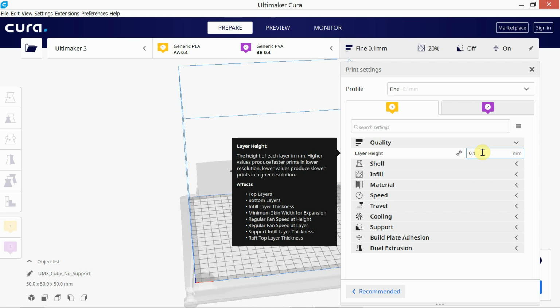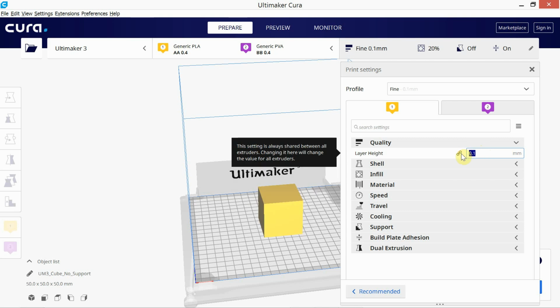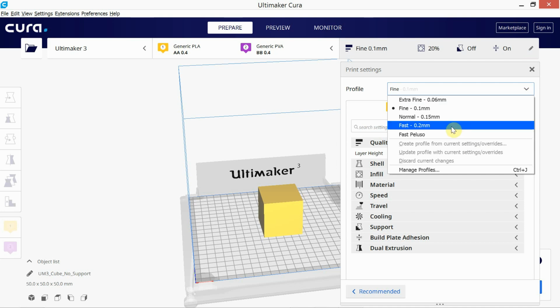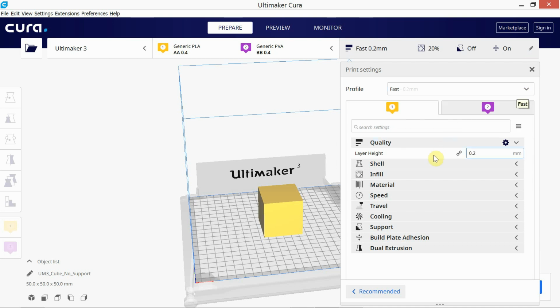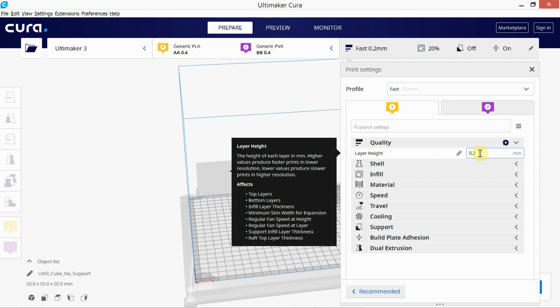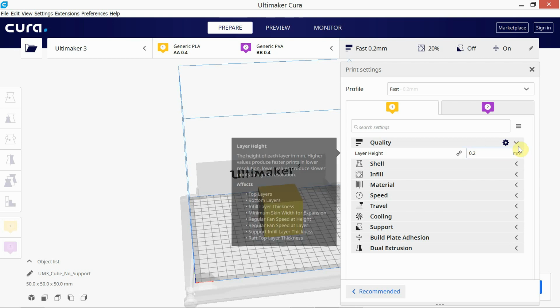In working with my architecture students, we're trying to look at design options. We're trying to iterate. So we want our prints out very quickly. In the beginning, we're not so focused on the quality. That's something we can do at the end when we have the design chosen, the design that we want. Then we can go to higher quality. Okay, so let's go ahead and set the layer height. I'm looking at making some custom settings. Now I could start with fast. And then my layer height is already going to be 0.2 millimeters. So that's going to save me some time, as we saw previously.